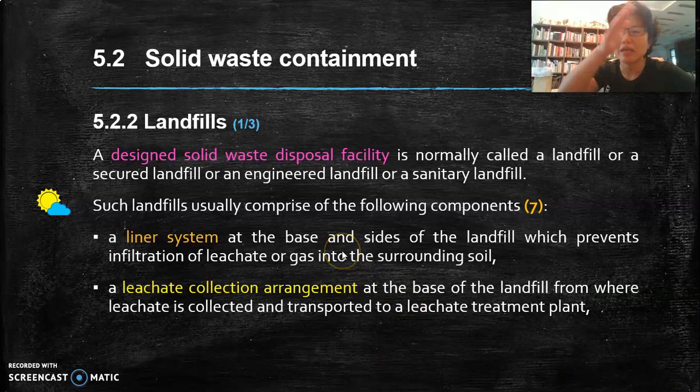of the landfill. So basically, you excavate into the ground, and before you start dumping your waste into it, you got to start lining it. And these liners are usually what we call the membranes, geomembranes. If you recall from our geosynthetic talks, these liners are essentially 2 layers of geotextile, so water could go through, but inside is a layer of this expandable kind of clay, usually montmorillonite. So once the leachate, which is in liquid form, goes into the liner, it will cause the clay to expand and seal out all the pores in there. So theoretically, none of the leachate, none of the liquid could actually puncture that layer into the ground beneath.